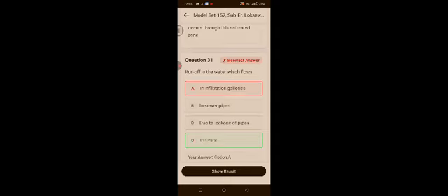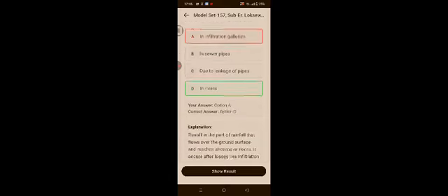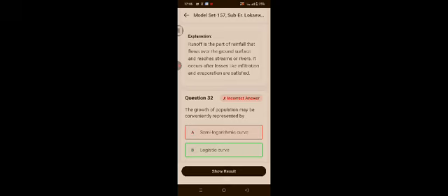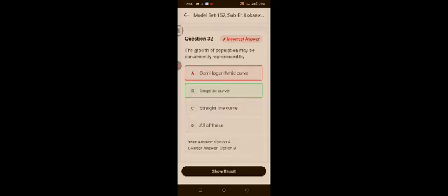Runoff is the water which flows in the river. Runoff is the part of the rainfall that flows over the ground surface and reaches the stream flow of the river. It occurs after losses, the infiltration and evaporation, are satisfied.